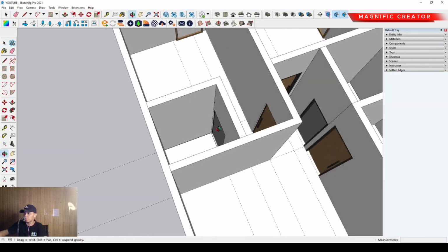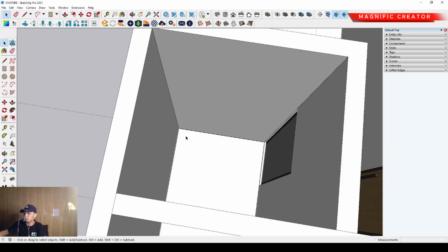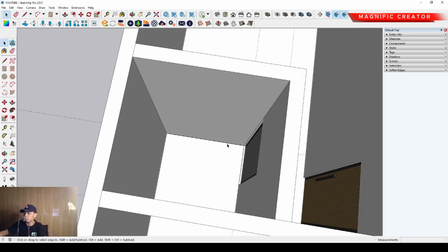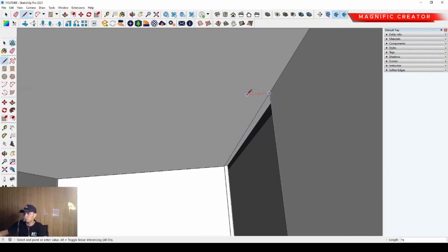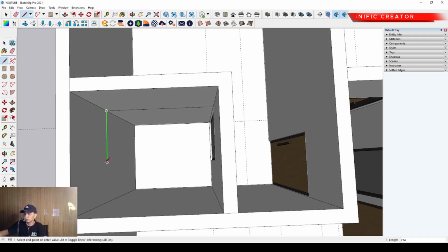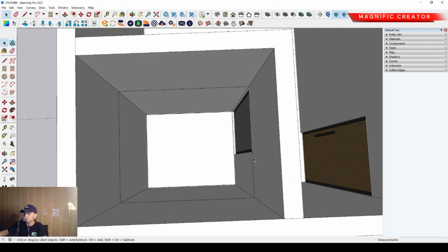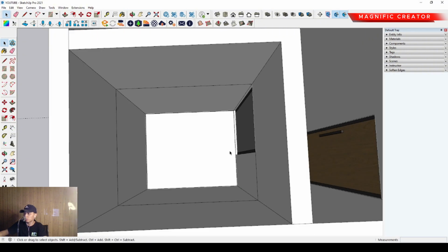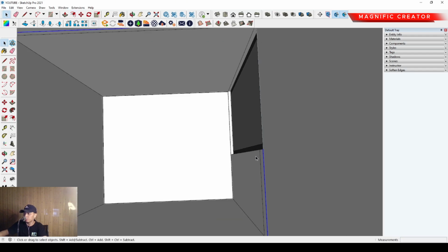Okay, and then we can make another wall element of this bathroom wall anyway. We can start from here and we can continue to make the other side of the wall. Anyway, sorry, we have to offset it inside around 20 millimeter.